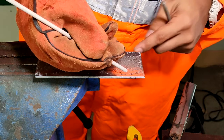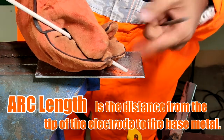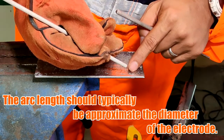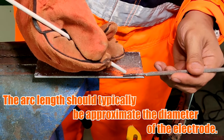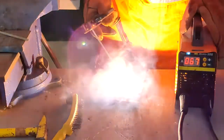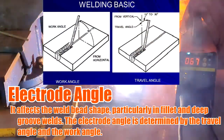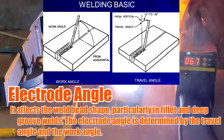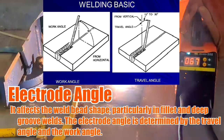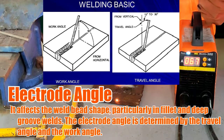Next is length of arc or arc length. Arc length is the distance from the tip of the electrode to the base metal. The arc length should typically approximate the diameter of the electrode. Another consideration is electrode angle. It affects the weld bead shape, particularly in fillet and deep groove welds. The electrode angle is determined by the travel angle and work angle.